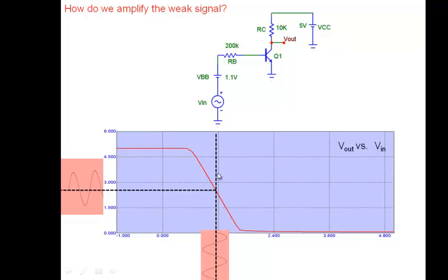So you're realizing that as I increase my input voltage here, eventually my transistor is going like this, increasing more and more here. Eventually what will happen is it will reach this edge. Once it reaches this edge, it no longer responds to input voltage. And you will begin to see distortion. Your sinusoid will start getting clipped at 5 volt. And once it reaches this, again it will get clipped. So you'll begin to see that there are limits to how large a voltage I can apply. After that, it will not work here.